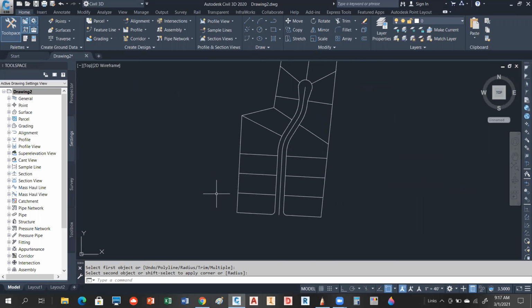Now, could you do that with the Civil 3D command curve? What would that be? Curve between two lines? Yeah, it's exactly the same command. It just has more variables built into it. Fillet only gives you the radius option, which is all I needed. But the Civil 3D one, like I said, is probably on steroids. It's got way more than you're using. So keep it simple, okay? When you're using stuff, utilize what works. And yeah, definitely you could use the Civil 3D thing, okay?